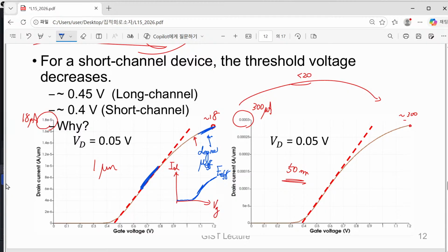Threshold voltage is nothing but whether we have a sufficient number of electrons collected in our MOS cap or not. That is the quantity of our interest. So therefore we wanted to kick out this part because its behavior is already severely affected by effective mobility.